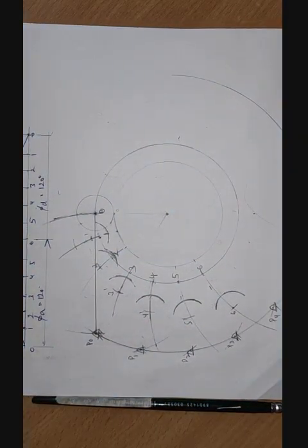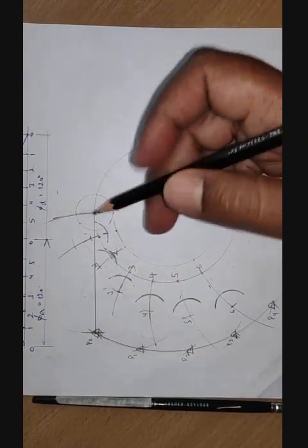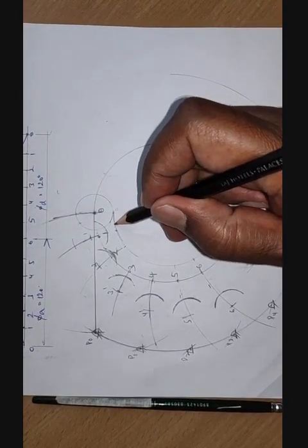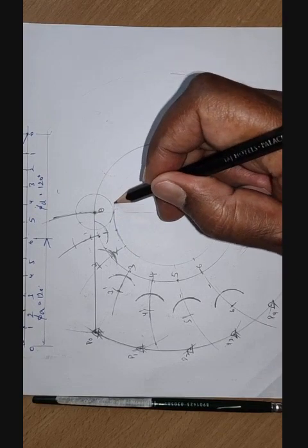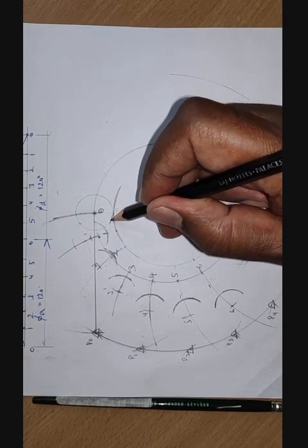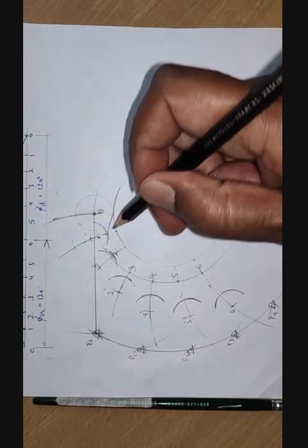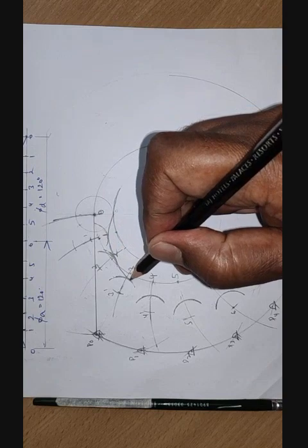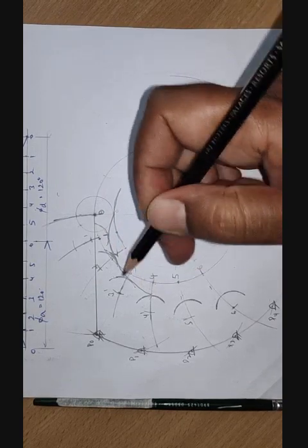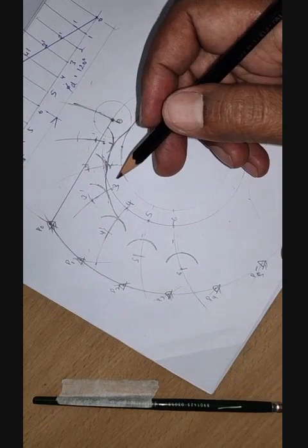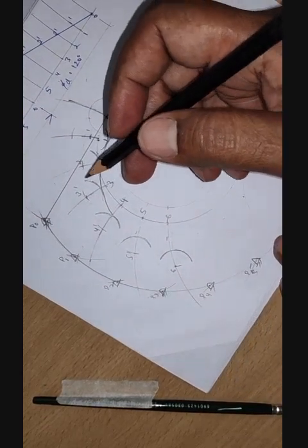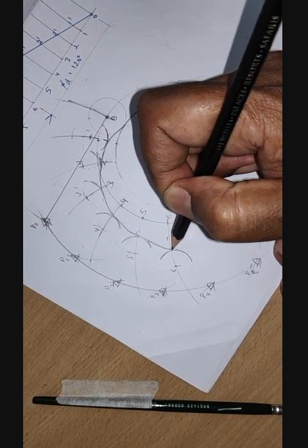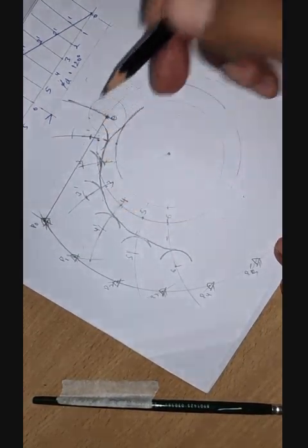So once the roller is complete, then to lift the roller by this height, the cam profile which was like this, sorry, it is the base circle. The cam profile has to be like this to lift the roller by this much. Again, the cam profile has to go like this to lift the roller at every point. So what I try to do is draw a curve like this through all these points here. So this is how you draw the cam profile.